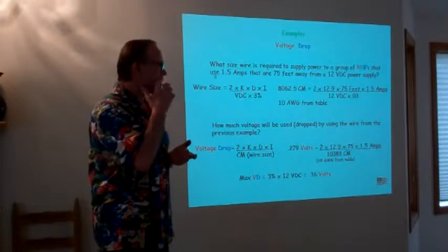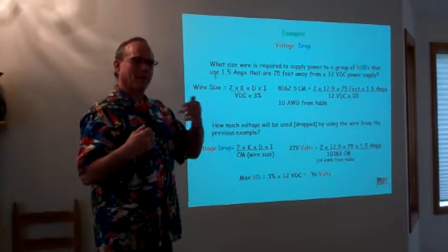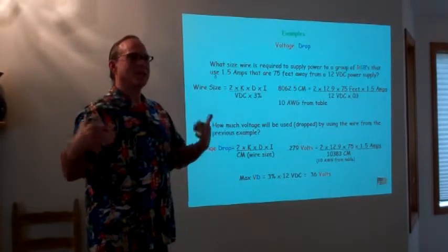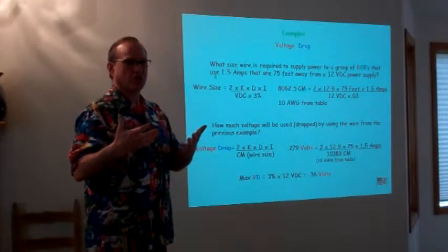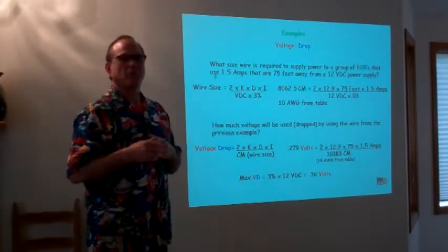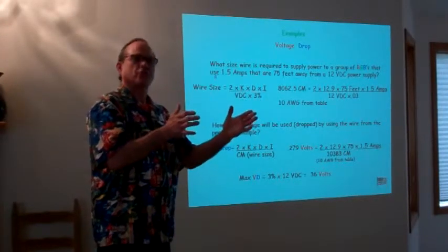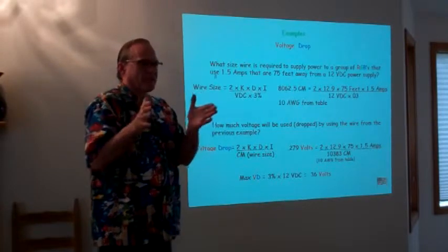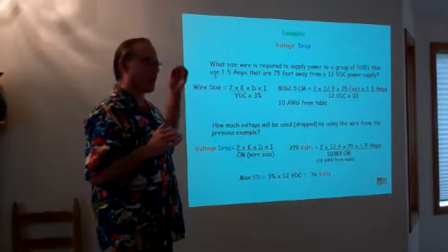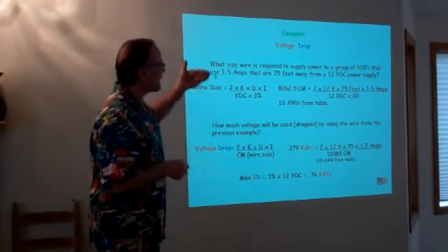That's true. Re-injecting basically just means that we're providing another power source, that we're boosting power. Typically in DC, you can't re-boost the power. You can't change it again. It's just what it is. And typically, as we'll see a little bit later, we have to keep in mind our length from our source to our string or to our load, and we have to adjust that based on what we need from our voltage and our current levels to give us our proper power out there.